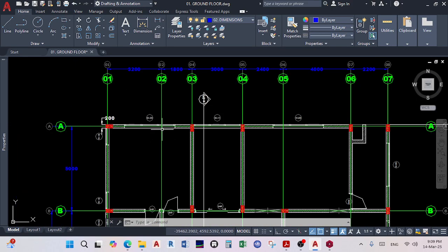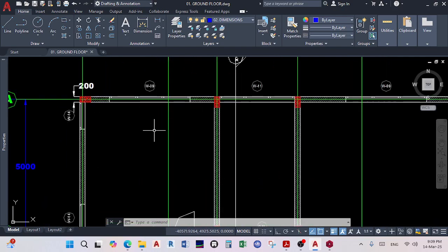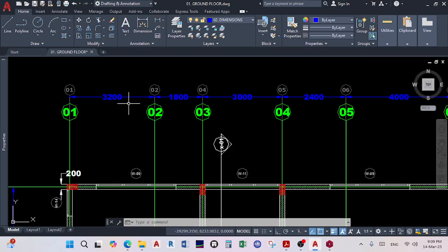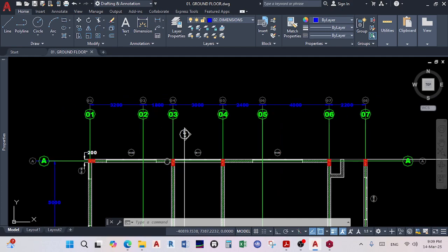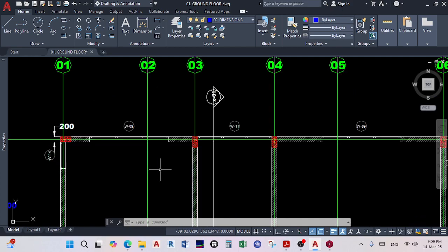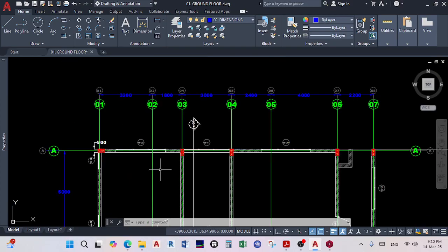And also, bear in mind, the architect has already designed these windows, these doors. For example, this span is 3.2 plus 1.8, which is about 5.0. So that's a span of 5. I know that if I use maybe a deeper beam, like a 200 by 400 or 200 by 600, according to my experience, it would be able to withstand a 5 meter span, right?